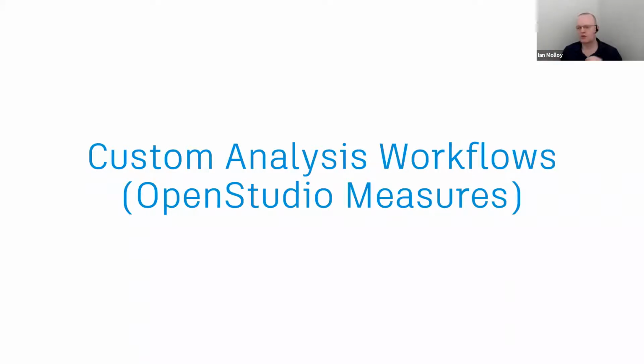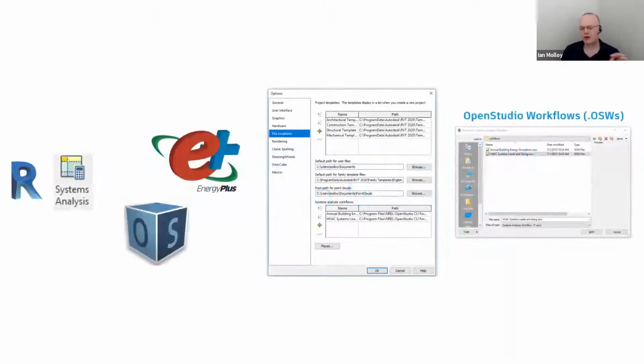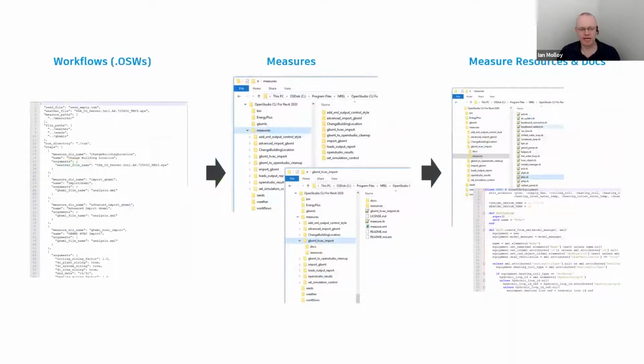All of those behaviors and all that logic is contained in OpenStudio measures or what we call a workflow file. You'll see that in Revit, if you look under file locations for systems analysis workflow, we provide you with 2. You can go and find them and open them up, and you'll see the scripting. For example, what's happening behind the scenes when you run that analysis is it's actually exporting GBXML, converting it into Energy Plus. It's applying any data that wasn't specifically defined in that GBXML.